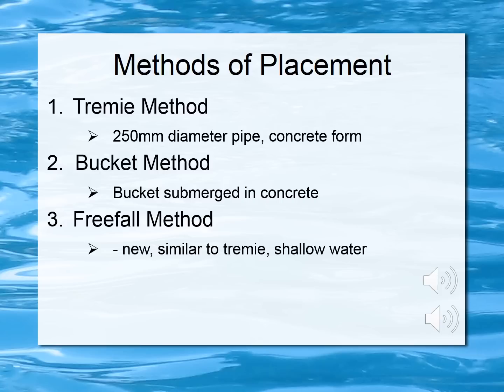from the bottom of the excavation inside, and that is lowered into the water or some other sort of formwork that you've created underwater, generally all the way to above the surface of the water, and you release the bottom of it. A hopper at the top ensures that the concrete goes into the pipe and there's no extra waste. Then you can remove the bucket.